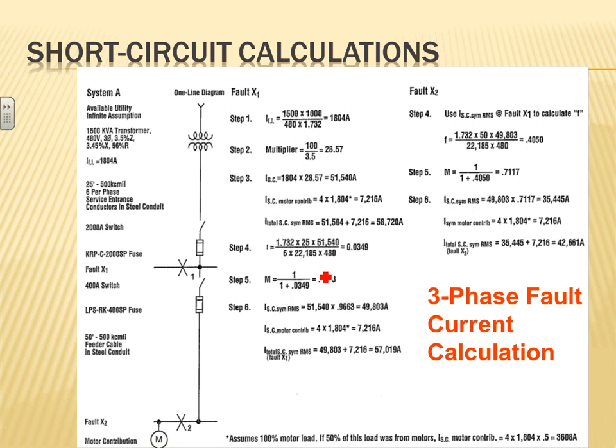I thought I'd throw in a couple of short circuit calculations by hand because you guys like to do that, for the ones who don't have access to SKM. Here's a couple of examples of short circuit calculations, and I think you have that one. This should be part of the PowerPoint presentation too. So here's an example of finding the F factor, and I'm not going to go through all of this one. I thought that's a really good example. I always show it to contractors who don't have SKM if they want to do something by hand to be dangerous.